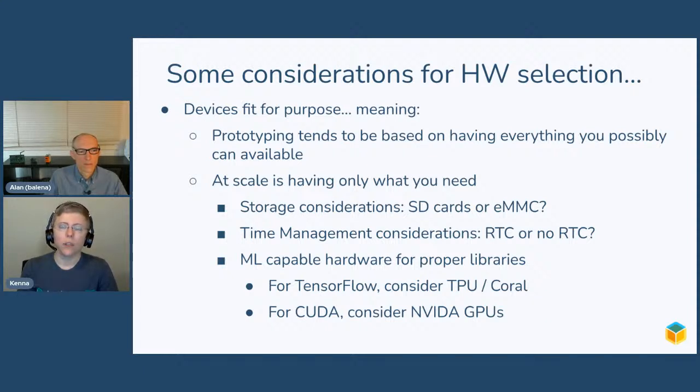And the reason is that in their particular applications, they know that they will run through the eMMC. They will wear it out for certain. And so an SD card replacement is actually the cheaper option than having someone go on site and replace that device, or try and desolder and resolder eMMC. I don't think most people would even bother. You'd probably just swap it.